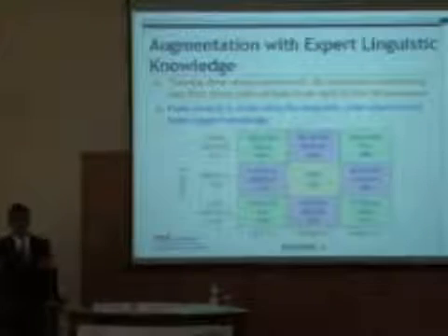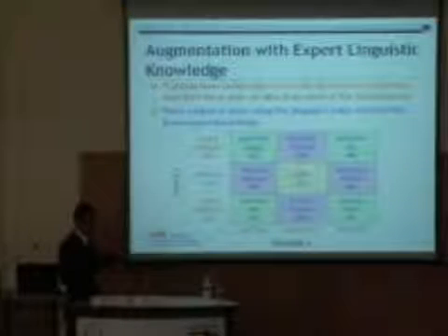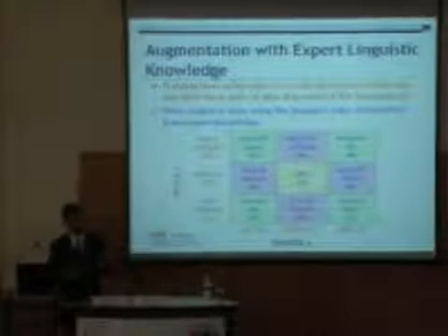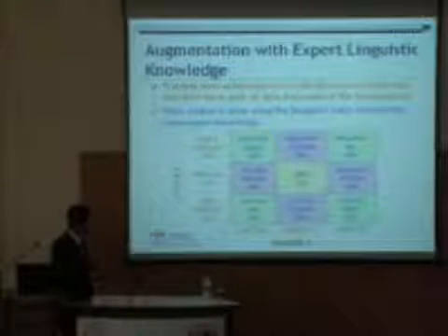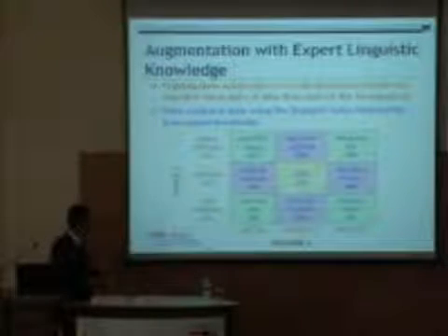Then we have 9 rules which are derived from experts as to how the truck has to be backed up. What is the optimal way to back up the truck? And we came up with 9 such rules. So if the position is left and the angle that it makes is left vertical, then the steering angle should be positive big. And each of these positive bigs and positive mediums and centers, lefts and rights, are symmetric Gaussian functions, which I've not shown here.